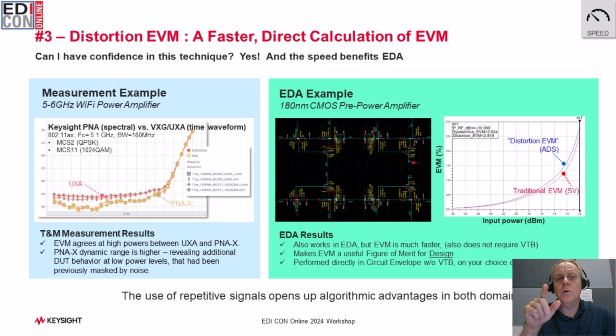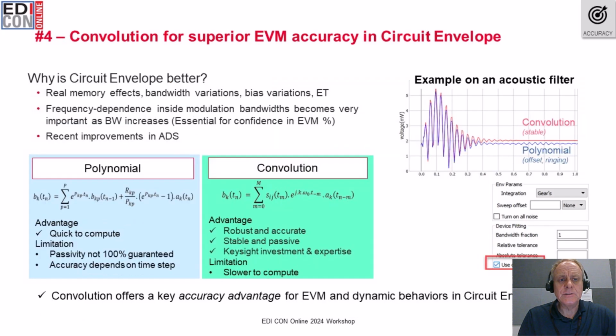So now you can do a sweep of power, a parametric scan, or even load pull. So it makes these features make envelope capable of doing quite a bit of modulation analysis at the point of design rather than leaving it to the very end as a verification step.